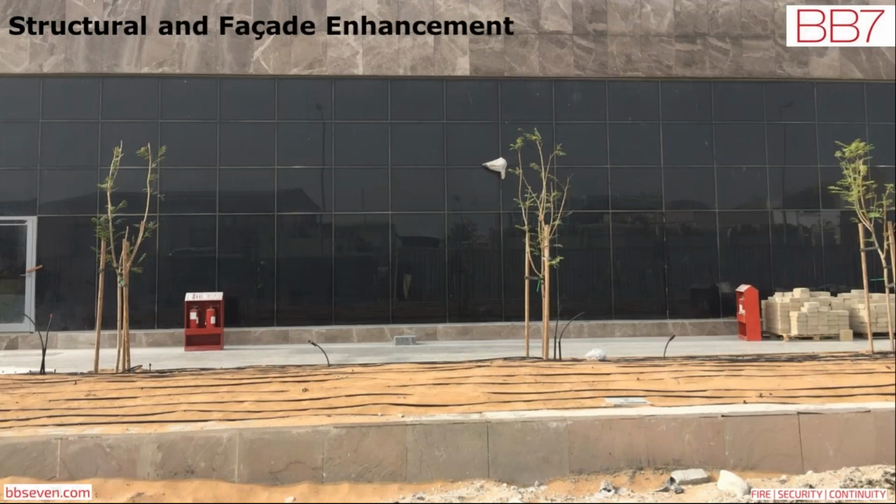And the same with the Façade. This is a luxury hotel in Abu Dhabi. Behind this is a 2,000-seater ballroom, and the distance from the road to the Façade was not sufficient to prevent failure of the Façade from a vehicle-borne device. And that would result in secondary fragmentation of the glass into the main ballroom, which was deemed to be unacceptable. Now, we resolved this by leaving the Façade as it is and created a solid wall behind, which resisted the blast and captured any fragmentation, protecting people inside.